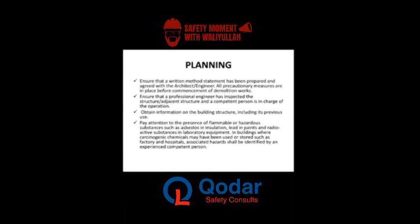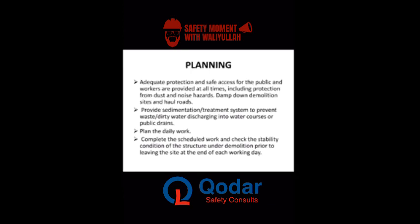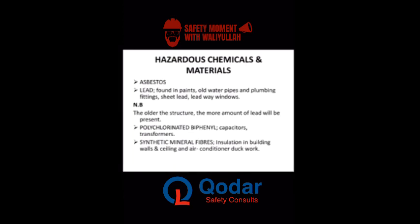It is also advisable that we put all emergency preparedness services in place. We also want to ensure that all our plans and suitable PPEs are provided. Ladders, cranes, equipment, and warning signs should be in place and in good condition. We need to also plan the work very well and make sure that all essential services such as water, gas, telecommunications, sewage, and chemicals have already been shut down before any demolition work commences.